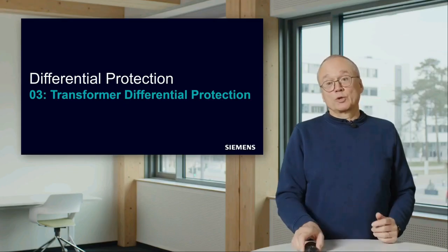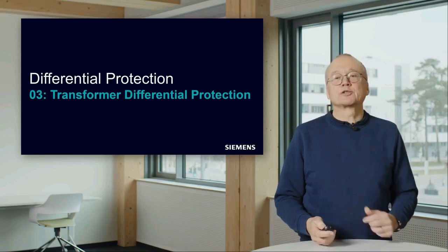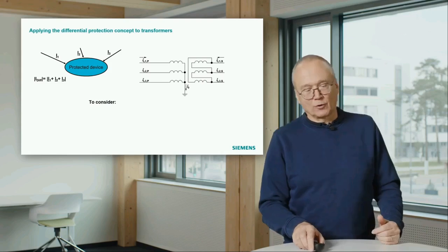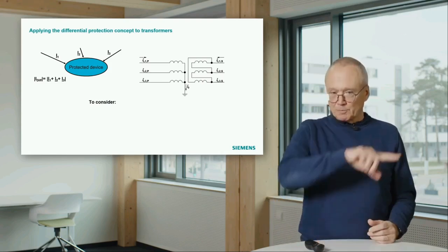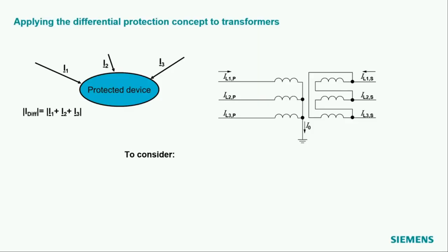Let's have a look into transformer differential protection. That means applying our differential principle to transformers. Remember the principle, we draw a circle around our device, measure all currents flowing into the device and calculate from that the differential current by summing up the currents.